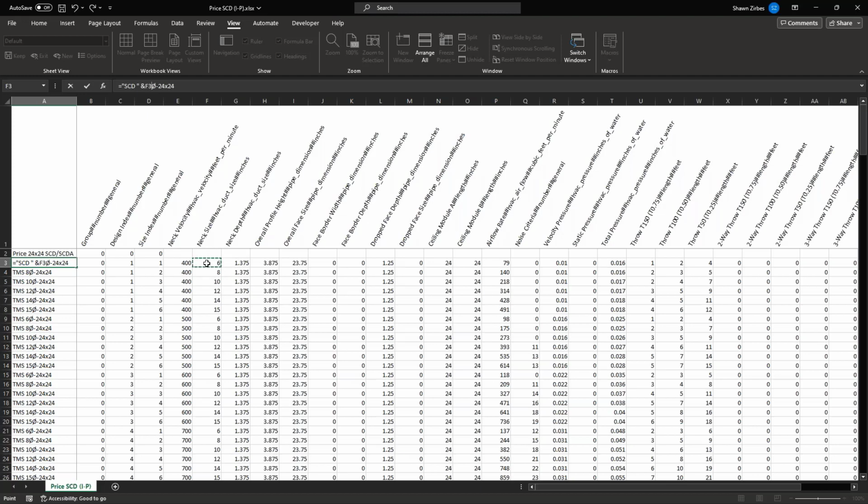So I want to use this explicit value here. This is the next size for that particular row. Now, right after that, I'm going to put another and symbol, and quote, the diameter logo, which I didn't actually need to copy apparently, and then I want to do the size over here, whatever the face size is. So I'm going to do and this, the ceiling module A, and quote X quote and ceiling module B.